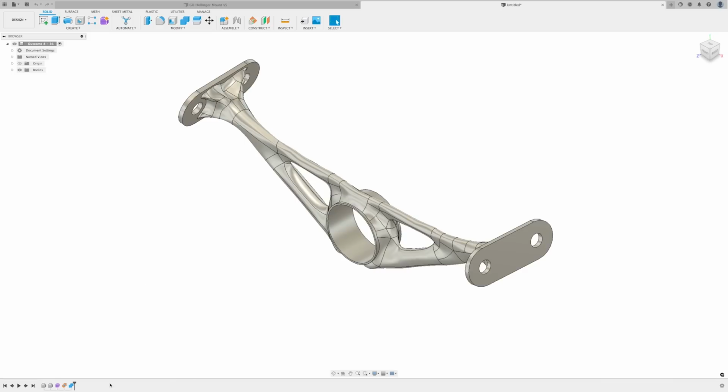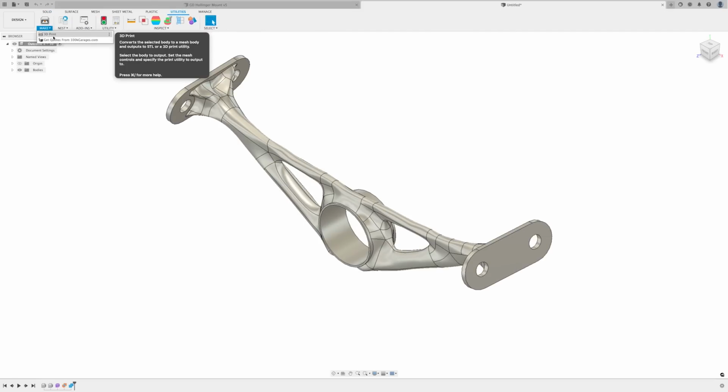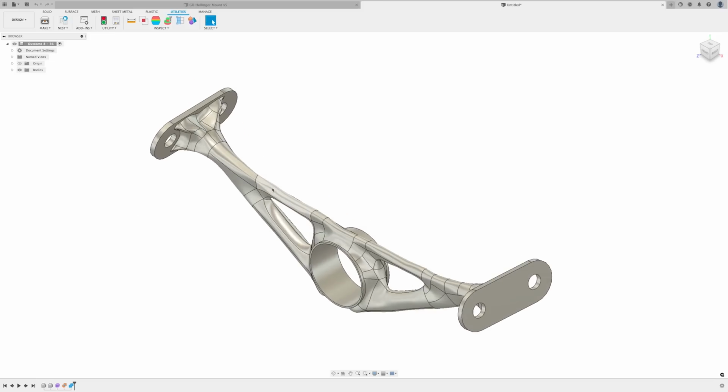Notice the processes in the timeline that build the design, including the preserves and obstacles. There's also an organic feature, which creates a complex outer shell, and then a boundary fill which forms the solid body. From here, we could export an STL file to 3D print the part, a step file to get the part machined, or just use it as guidance to create a new model that can more easily be created with other manufacturing methods.